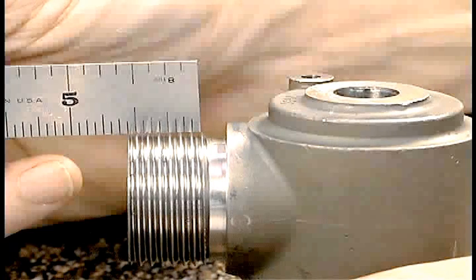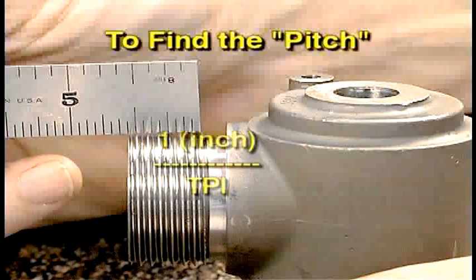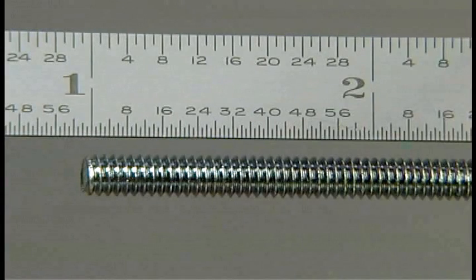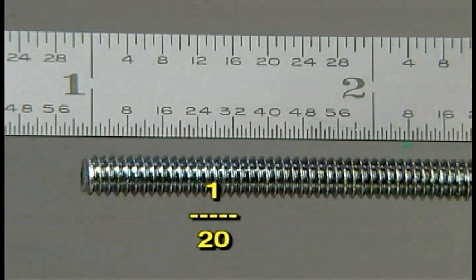Since the TPI is the number of threads in 1 inch, we can simply divide 1 for 1 inch by the TPI number to find the distance of one thread, in other words, the pitch. For example, on this 1/4-20 screw, divide 20 into 1 inch. The pitch of a properly formed 1/4-20 screw thread is therefore 50 thousandths.